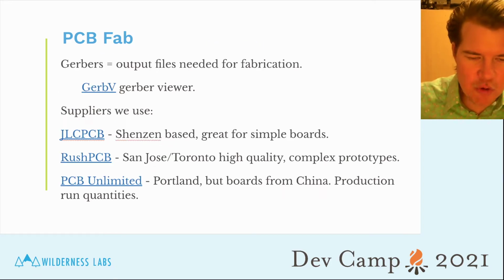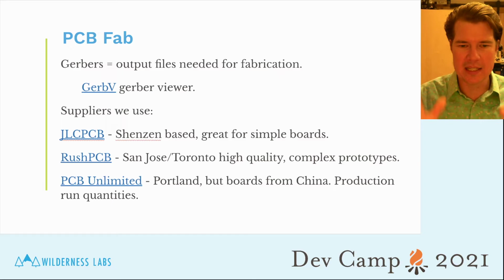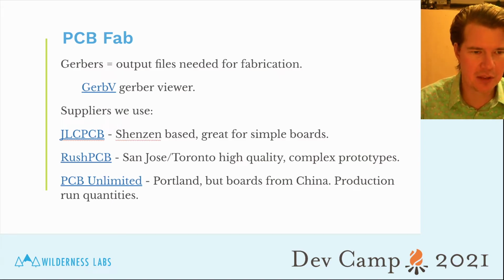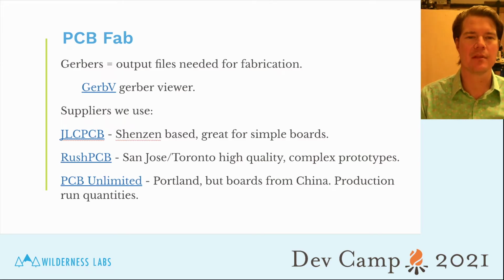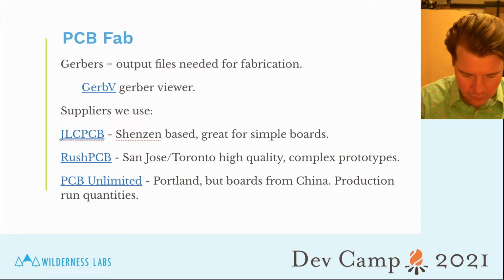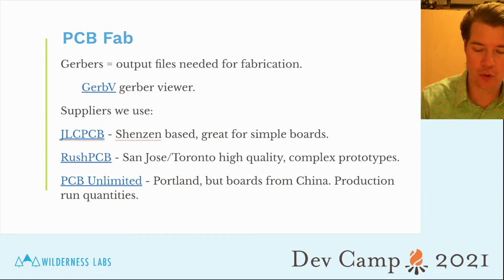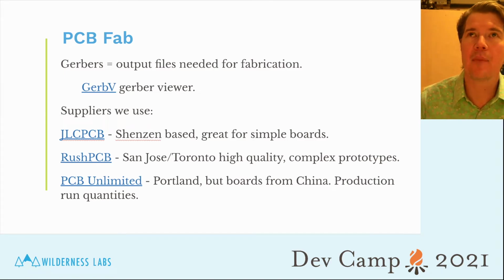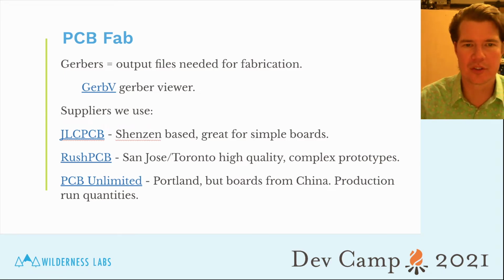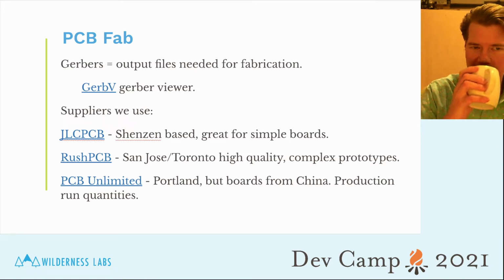Now, once you've created a PCB design, once you've done the layout, it's time to order that to fabrication. And in order to do that, you output Gerber files, and those are drawings for each layer, and a PCB fabricator will know what to do with those to make a PCB from that.